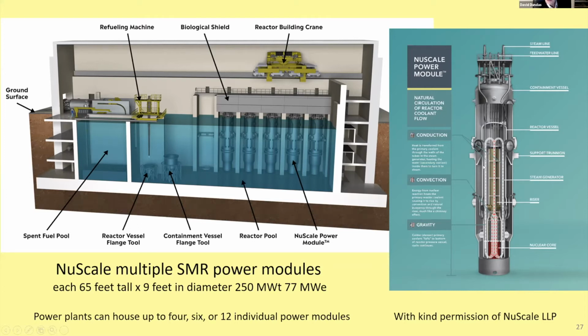And in this area, this heats up the steam. The steam pipe comes in from the outside and goes out, but this heats up the steam. And in doing that, the water falls to the very bottom and then comes up the center and round. So there are no electric pumps to fail, which adds a bit of extra safety.